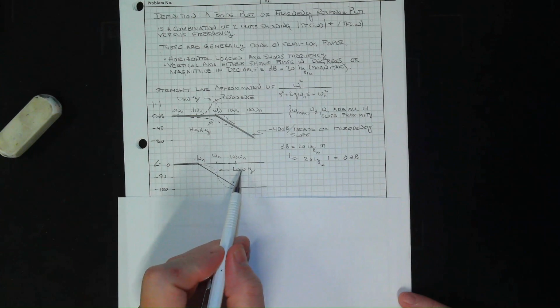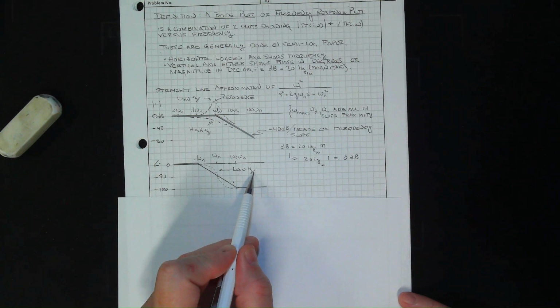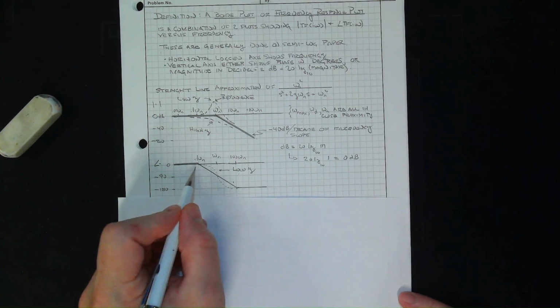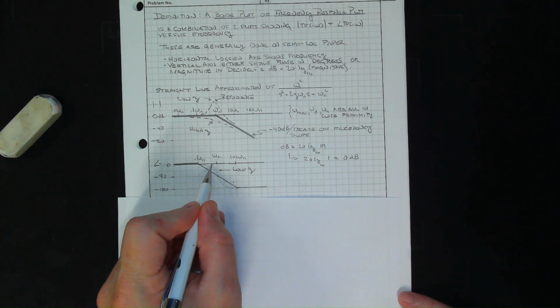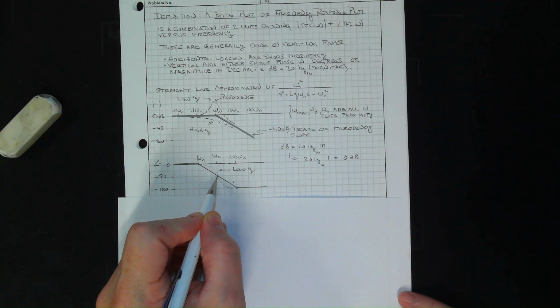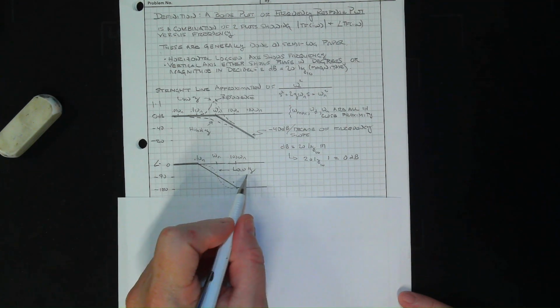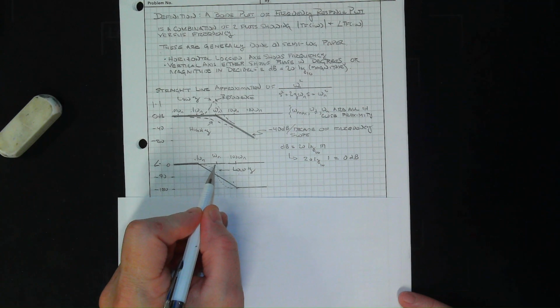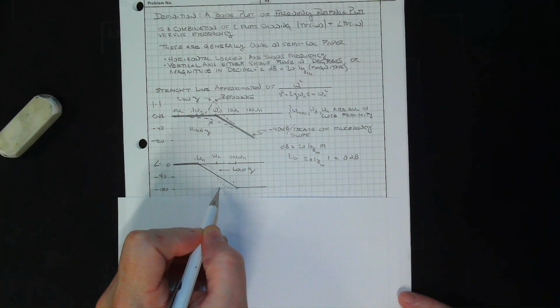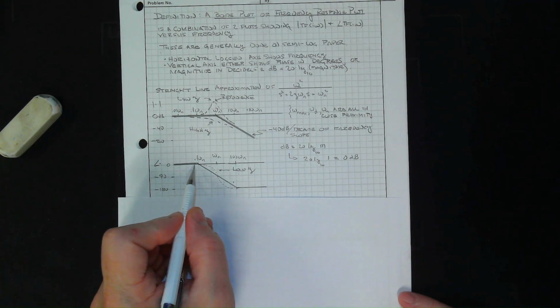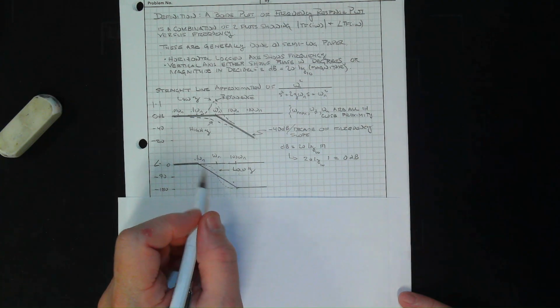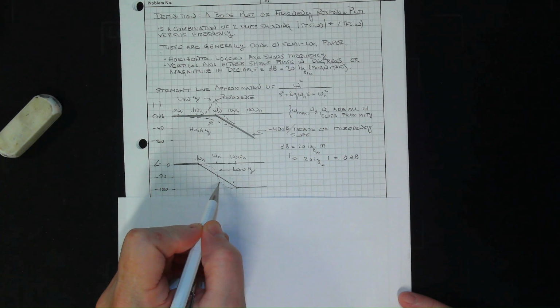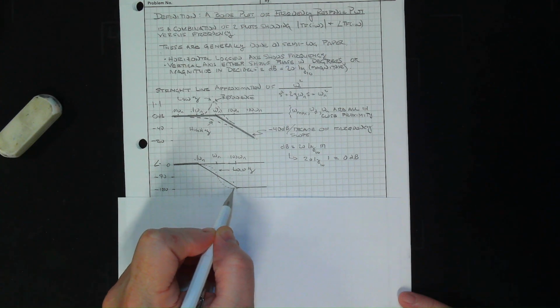All right. If you have low damping, here's what happens. This flat line continues longer, and then it just dives down through omega n. The lower the damping is, the more it wants to go right up to the edge and then just go straight down. So if you have damping of 0.01, it'll go really close to omega n, and then it makes sort of a right turn at Albuquerque, drops down, and then it just levels out there at minus 180 roughly.